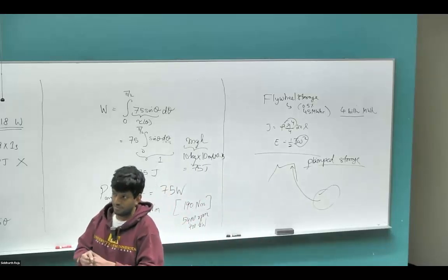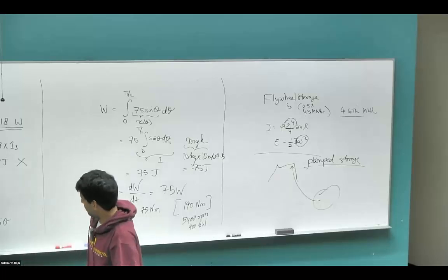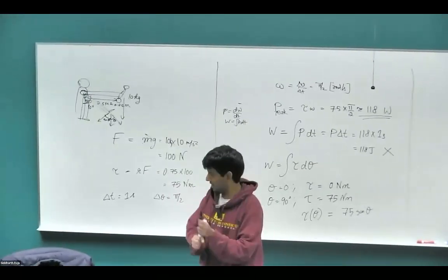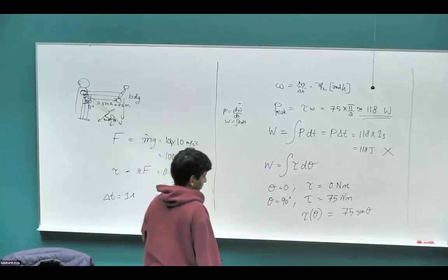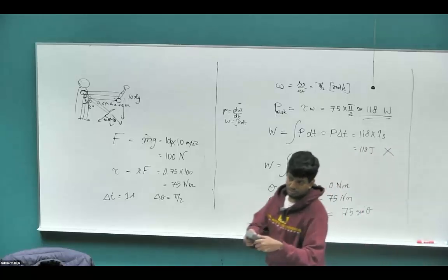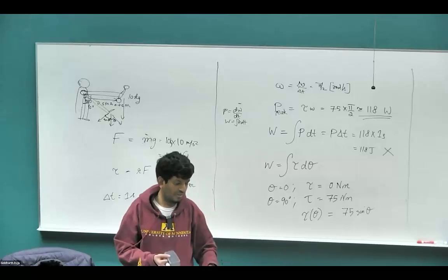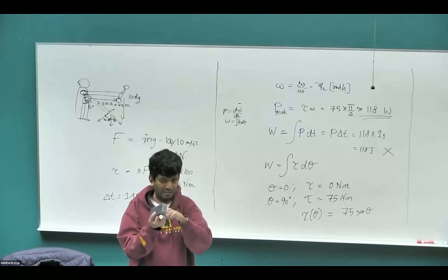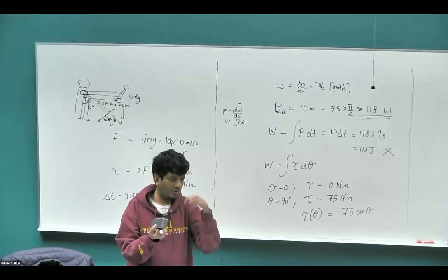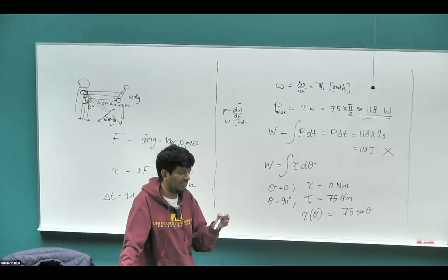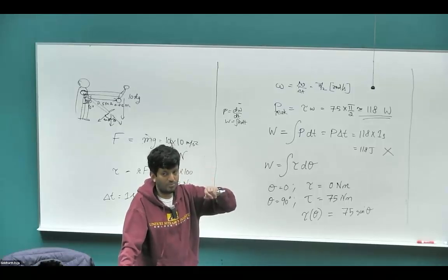Yep, there are just mechanical limitations to being able to make something like that. Perfect. There are two problems. First, we have bearings which could fail. We don't have systems that can do very high speeds. That's the area the professor in mechanical engineering is working on, basically using a magnetically levitated system. The rotor right now, in the motors we had on the table, is not floating in air. There is an air gap separating the rotor and the stator, but there is a bearing attached to the rotor, which rests on the stator. So the bearing can only rotate at so much speed before it starts to break down. That's the biggest limitation on how fast it can rotate. So if you can magnetically levitate this rotor, then there is no limitation from the bearing.